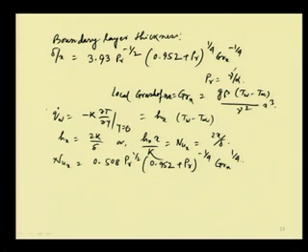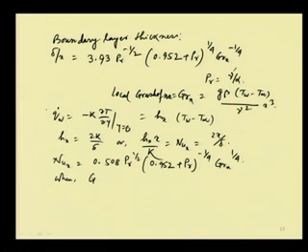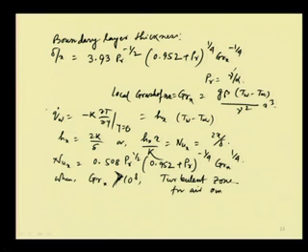This Grashof number is like the Reynolds number in forced convection, which we have already seen, and it dictates the flow conditions depending upon its values. When the Grashof x is greater than 10 to the power 8, we call it the turbulent zone, and this is for air over a vertical plate.